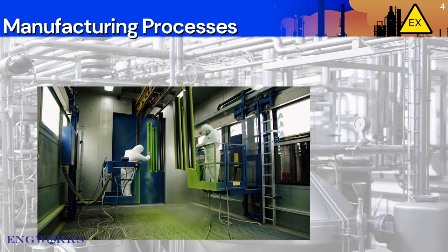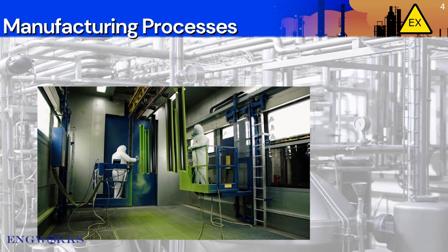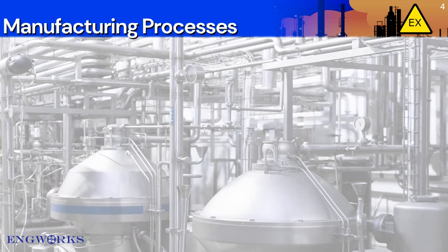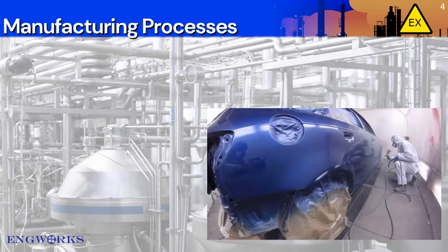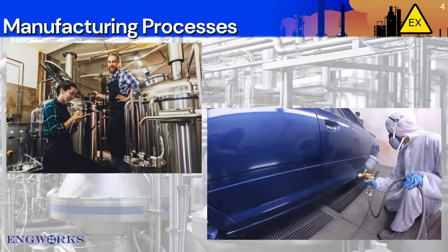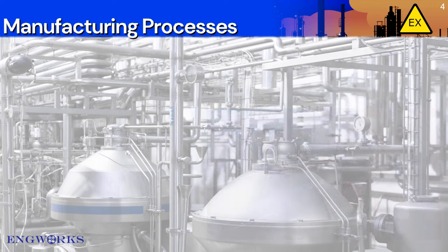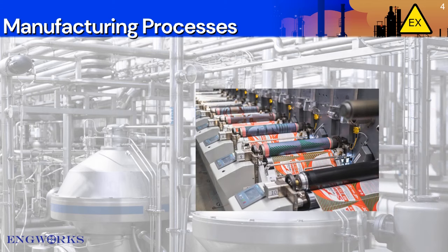Many common manufacturing processes use flammable materials in their process. Examples include spray paint, distillation, solvents, and dipping applications. Perhaps the hazardous area may be a small part of a larger process. It still requires evaluation to ensure that no ignition sources are placed within the vicinity of the hazardous area.